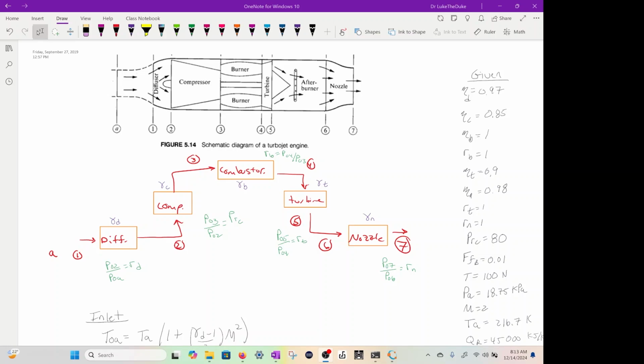What we're trying to do is find the exit velocity, find the fuel ratios, and find the performance of these types of engines, so we can possibly change the size, change the shape, change the pressure ratios, and try to get improvements to non-ideal cases. So that's why we have those adiabatic efficiencies, why we have pressure changes, stagnation pressures, because they deal with losses.